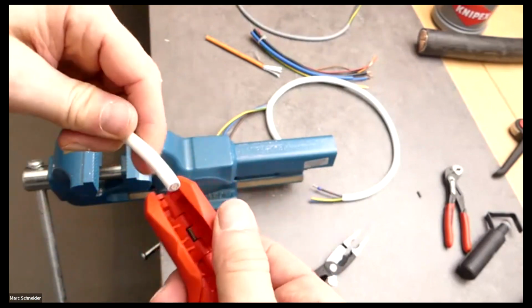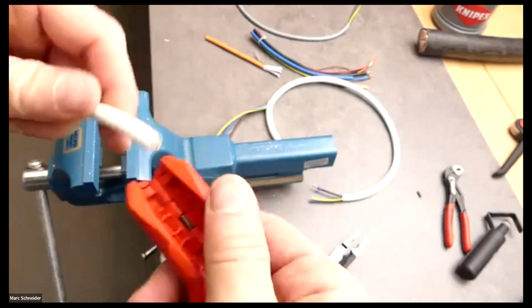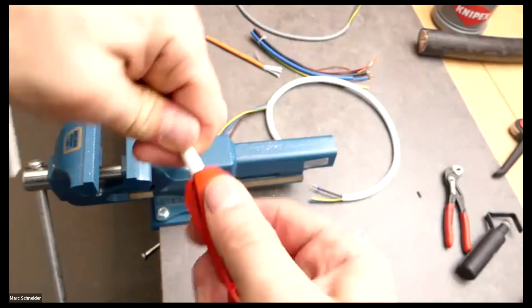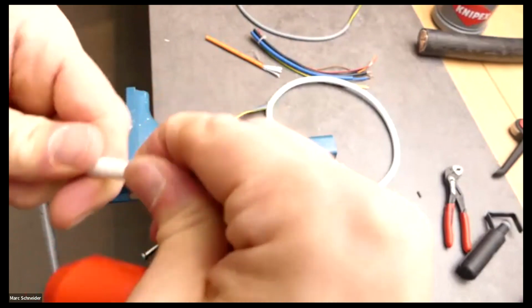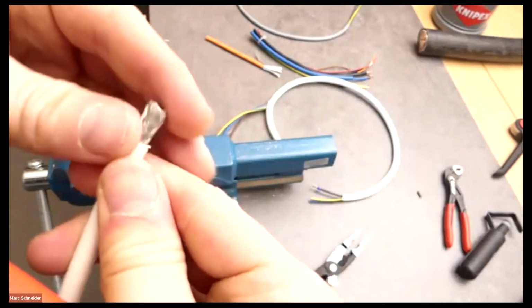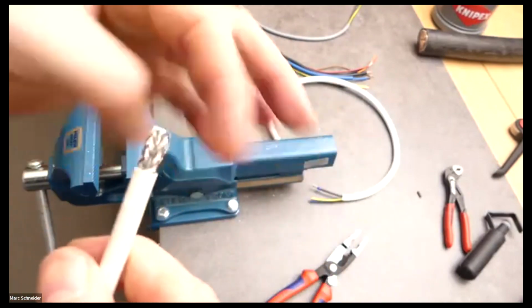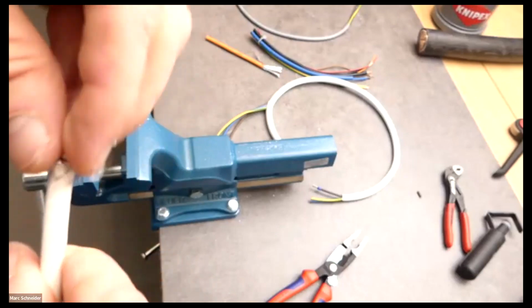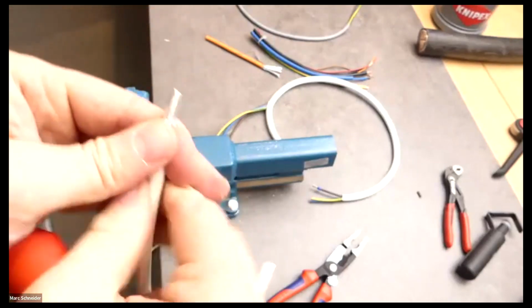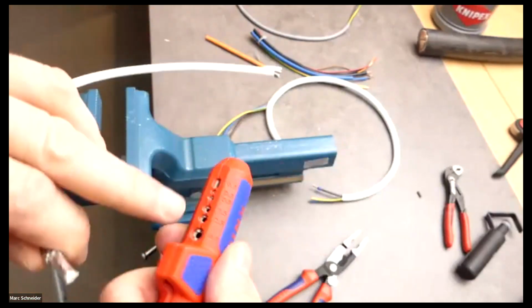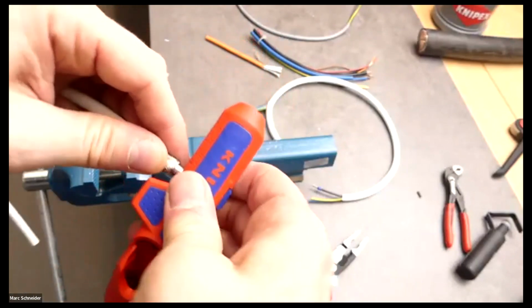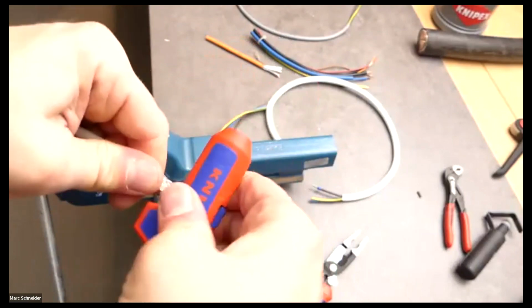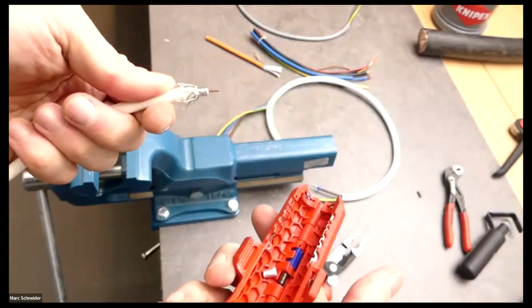The first cut you do here in the shorter side, around 12mm. So now we have here the aluminum shield. Depends on the connector. You leave it in this position or you do it in the back, like this here. And now you go in the hole of 4 square millimeter, around the half, 6mm length, and do the second cut, this, and that was it.